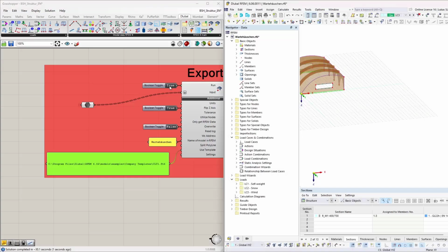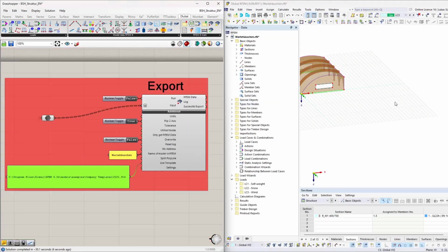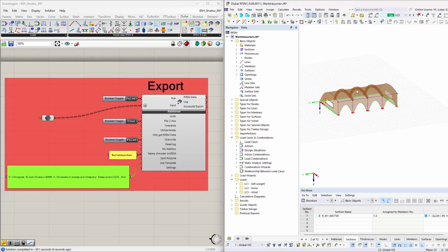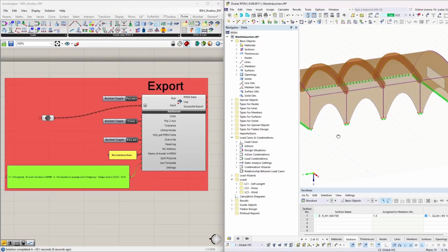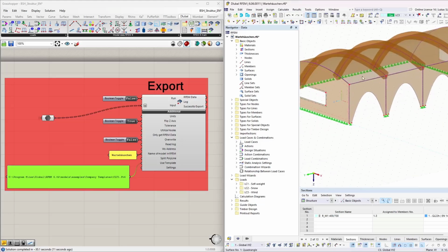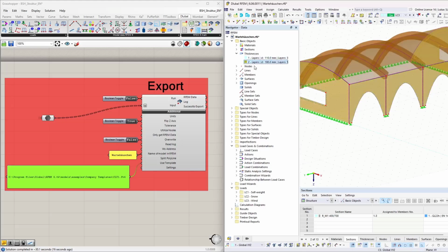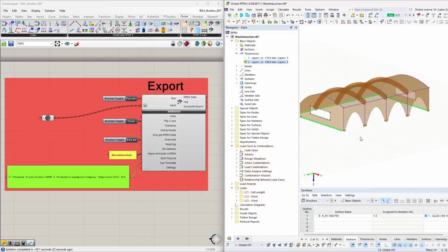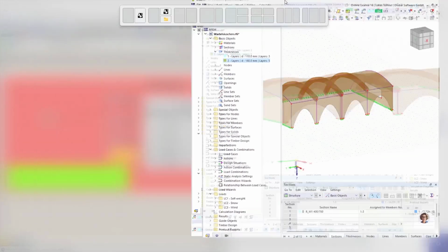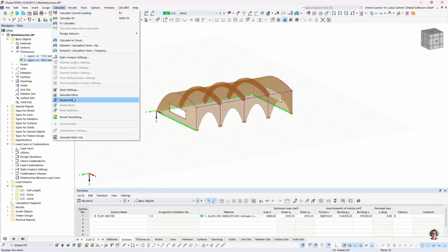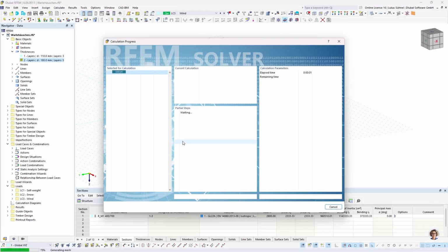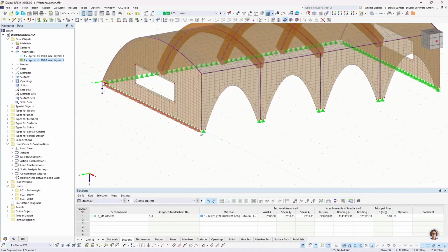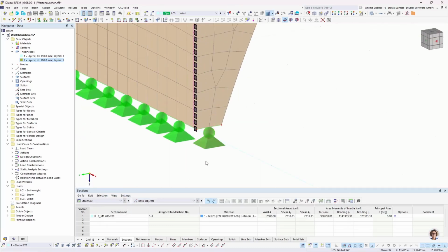All right. I disconnect the connection and I can see my file here. I have the geometry that I expected, my surfaces with the openings, my thicknesses with these layers that I defined before. And that's already a file I can calculate. Let me maximize it for a second. I can generate the mesh. In this predefined algorithm, I used the mesh refinement of 0.2 meters. That's why I have just 2 elements and not 3 over the width.